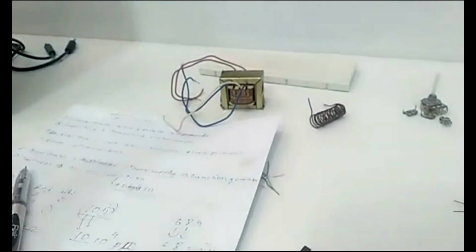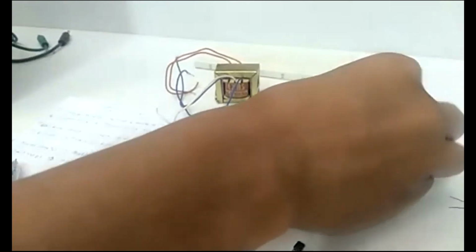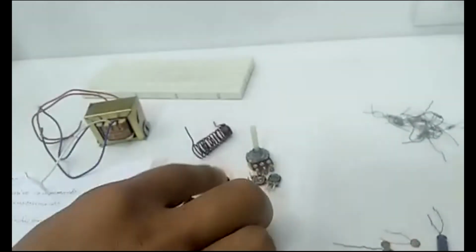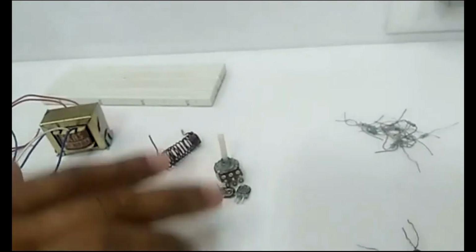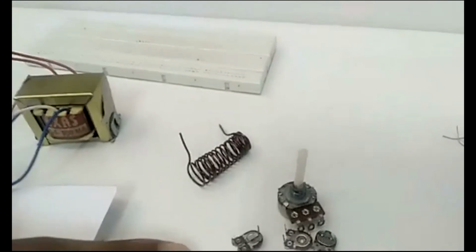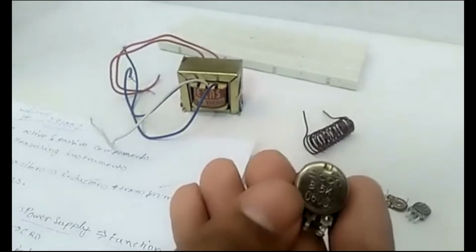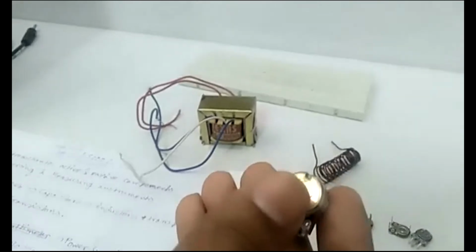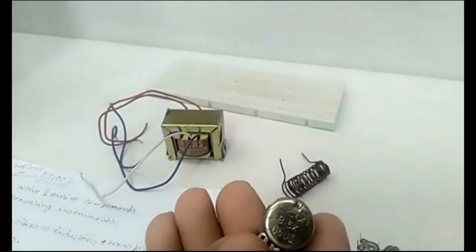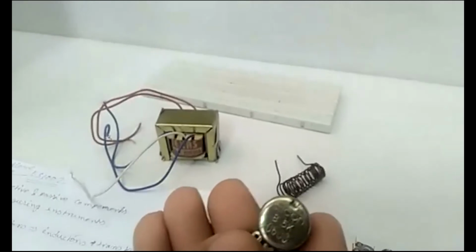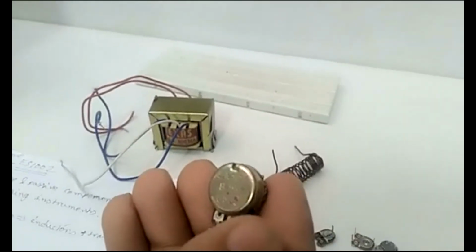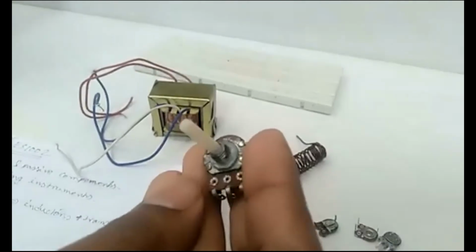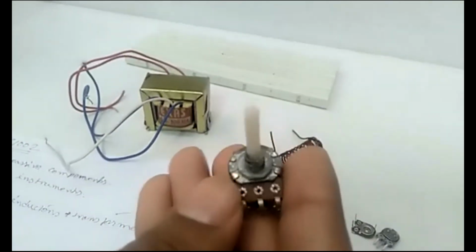We also forgot to tell you about the variable resistance. Variable resistance, or potentiometer (pot), we also have, and it will be very useful for our experiment. In case of a variable resistor or pot, the direct value is written. Maximum value will be 5 kilo ohm. I think it is visible to you. So the maximum resistance it can provide is up to 5 kilo ohm. Then, how to use it as a variable resistor.